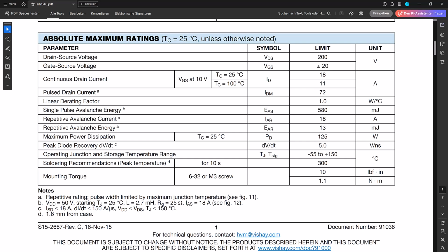And here I have to be very direct with you, because it's a trap every beginner falls into. 125 watts does not mean 125 watts without a heatsink. That number assumes you keep the case at 25 degrees Celsius, which is physically impossible in free air. But the takeaway I want you to leave with now is real maximum power depends on what you have mounted on the transistor, not on what page 1 says.